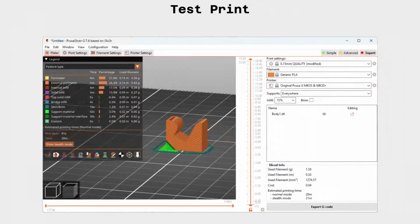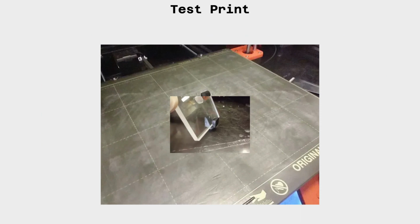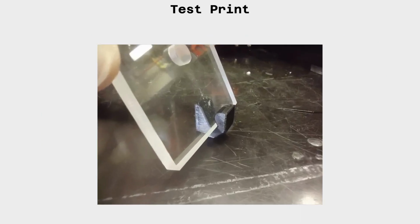So I'm using this just to cut out extra material and give this thing more shape than just a rectangular piece. And now I'm just going to be test printing a small section of this just to make sure it's actually able to hold the acrylic. I'll get into more details of 3D printing in the latter half of this presentation, but I've essentially just test printed it and seen if it can fit into the acrylic, which yes it can. It's a little loose, but this works for our purposes. If I found it too loose or too tight, then I would simply change the offset amount and reprint it to see if it fits better.